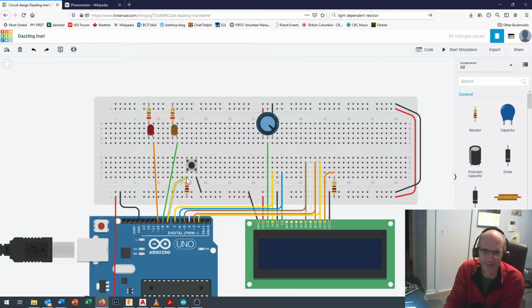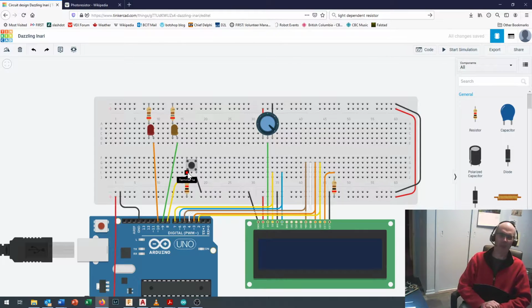Okay, don't go trying to stuff two things into one hole. In the real world, it doesn't fit nearly as well, but I think TinkerCAD's going to let us get away with it. So that resistor is going from our positive line right here in here, meaning that unless the switch is closed, we're always going to be positive right here. And then when we close the switch, the electricity is going to flow down here. This point is going to become 0 volts.